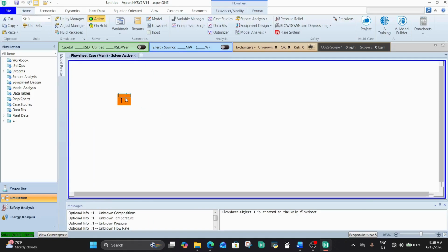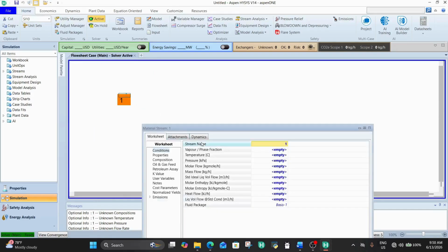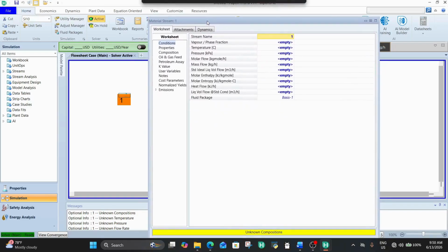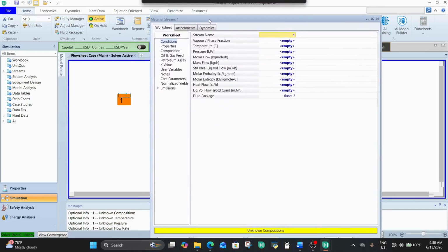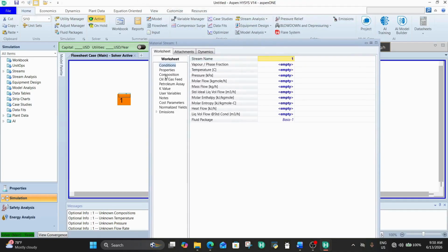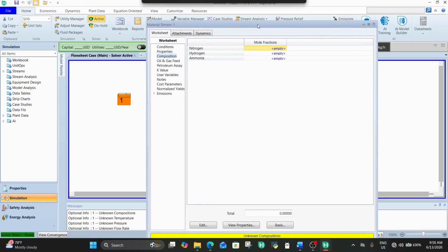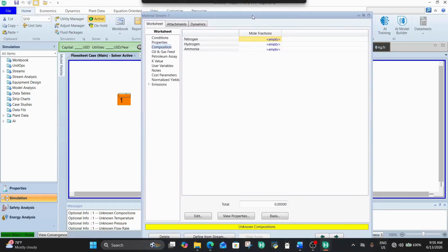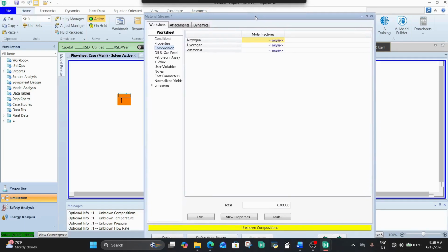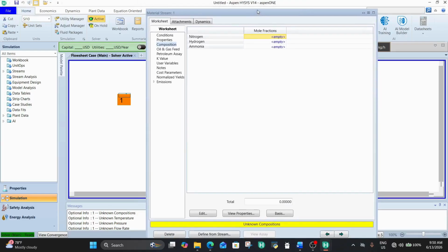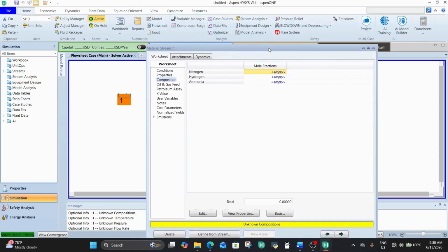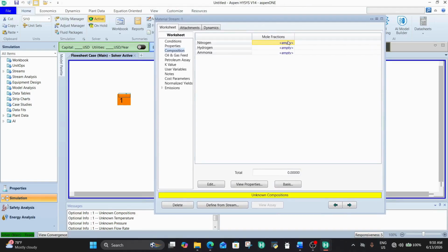And for today, our fluid package of the day will be PRSV, not the very versatile and regular Mr. Peng Robinson. This is his elder brother. PRSV stands for Peng Robinson Stryjek-Vera. It's more practical for our particular simulation today.